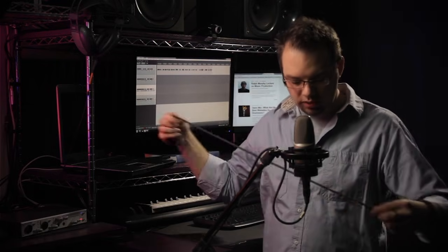And so when you undo this, you'll find that the cable has a twist in it. See, if we put this cable together, it wants to be twisted together. And that means that there's a slight twist of the cable over the length of it. What this means is that your cable will never ever lay flat on the ground. And that's bad because cables that don't lay flat are a tripping hazard. And the long-term effect of this is even worse because if you leave your cables wrapped the wrong way, you are leaving them wrapped with all kinds of twists in them.